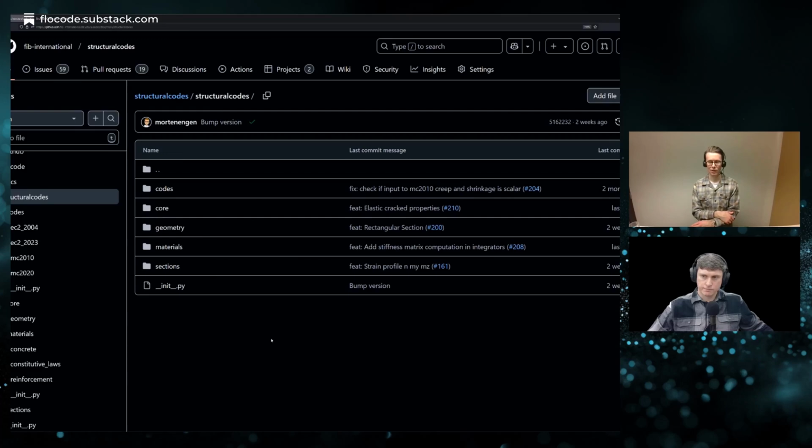However, I think in the ACI code you're entering more characteristic or representative values, and then you apply the partial factor on the response, so on the moment capacity, if I'm not mistaken. Yes. And you have different factors for different situations.